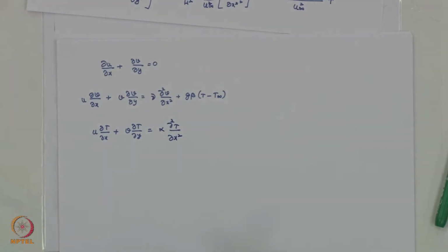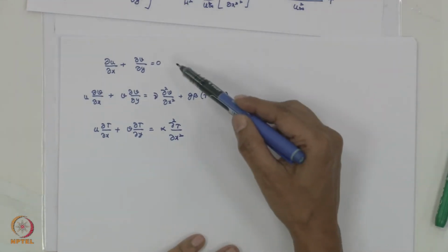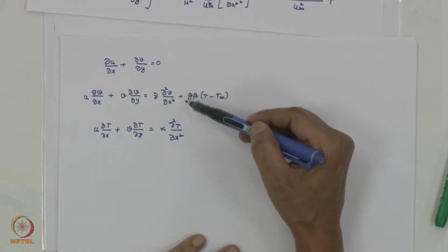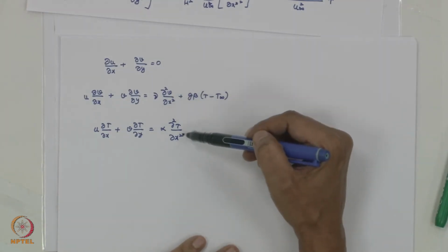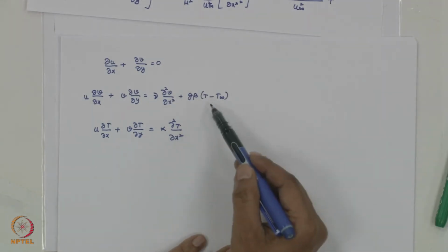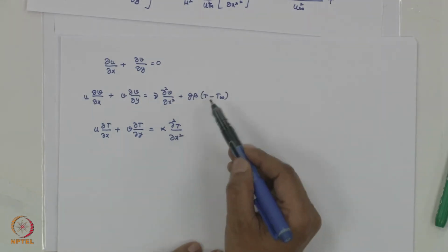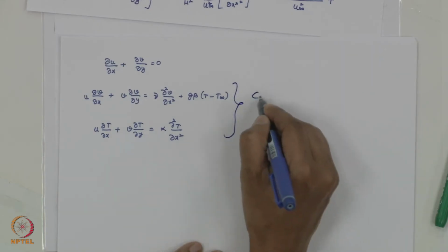See, please notice, in forced convection we could solve mass and momentum together and then take that velocity distribution and put it in the energy equation and solve the energy equation. But now that's not the case. T is in the momentum equation itself. That means these equations are coupled.